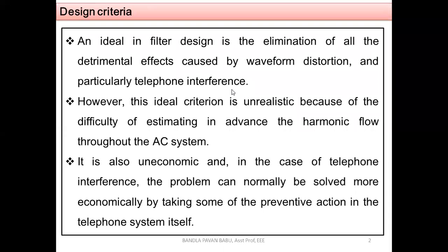Earlier we have seen that these are either railway signals or communication signals. Of course, if the power lines and the communication lines are very near each other, this is going to interfere, so we need to calculate that.